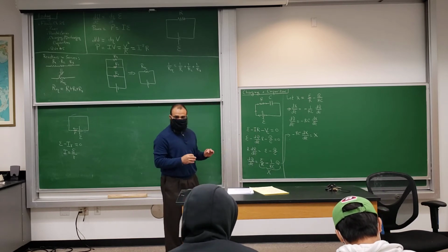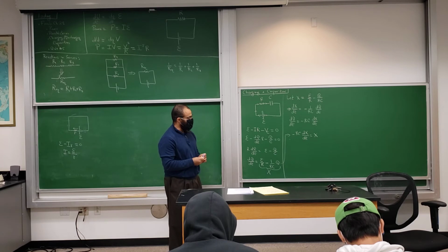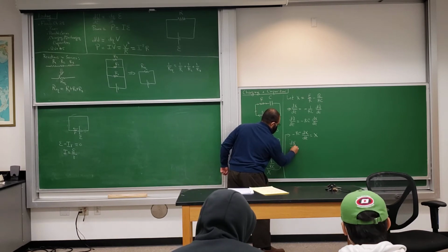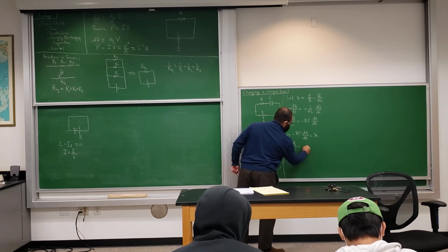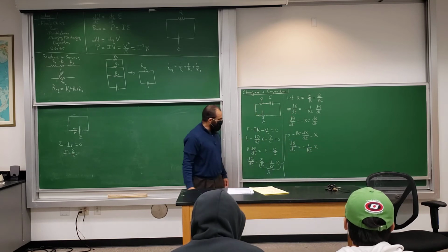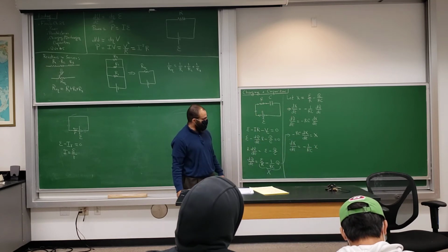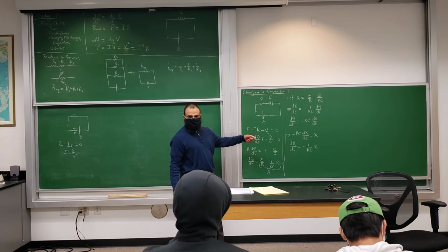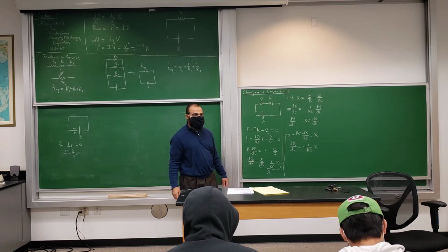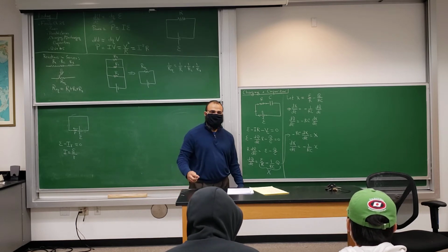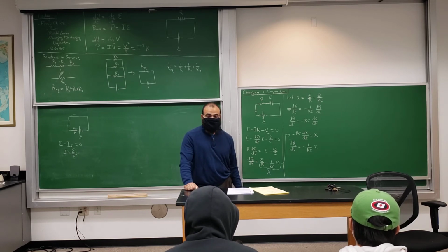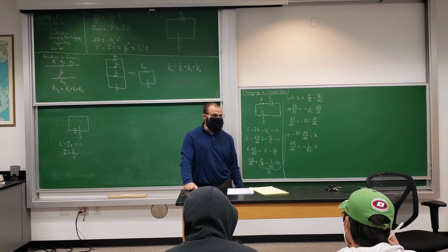We will go back to the original variables in a second, but for now, that's what I have. So dx dt is equal to minus 1 over RC times X. Now you can integrate this, or you can just think about something: you take its derivative, you get back the same thing multiplied by a constant. What is that thing? e to the something, yes. It is the exponential function.